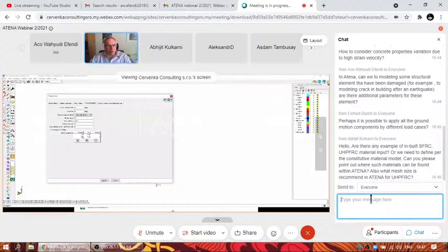Because we need to define these two parameters, ideal is to define this psi for two eigenfrequencies, typically, for instance, the first two. We define the omega for the first two frequencies, and the corresponding psis. They can be, of course, different, but it's 2%.